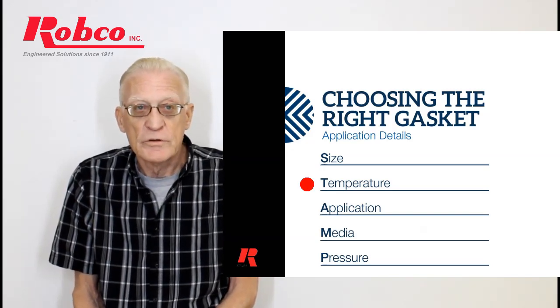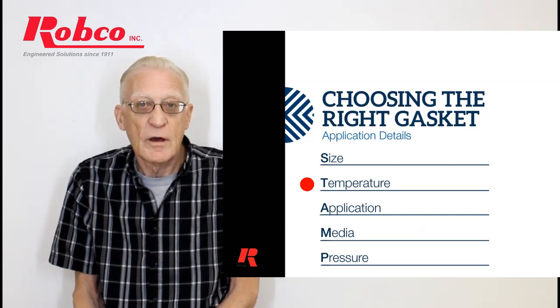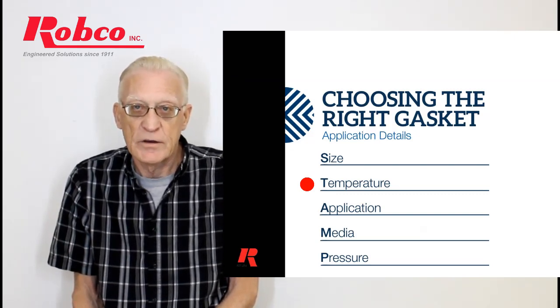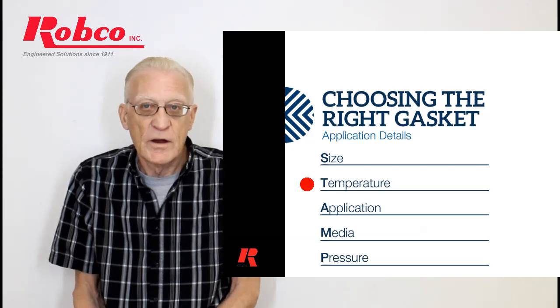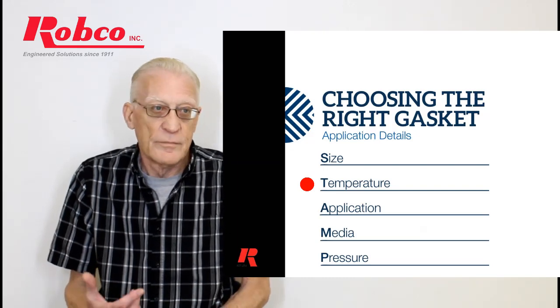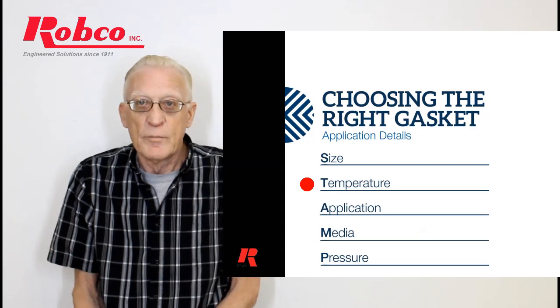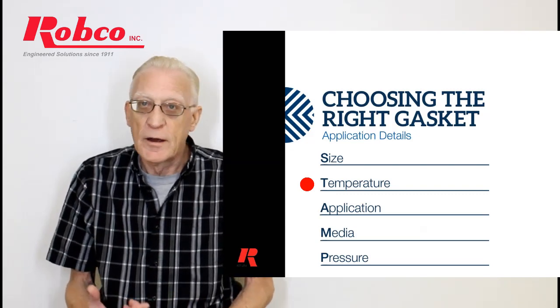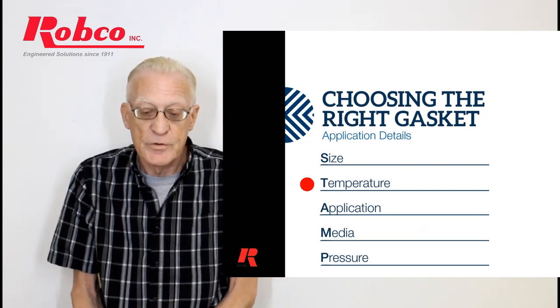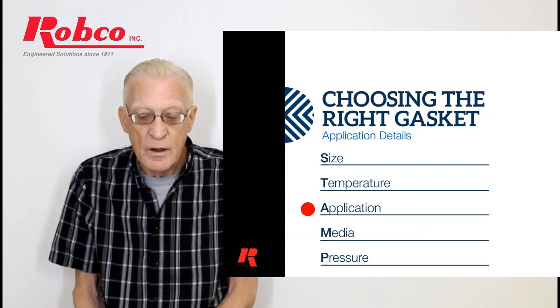Temperature, extremely important. Temperature, of course, they all have limits. I believe in safety factors. If it's 500 degrees, and the gasket's good for 500 degrees, well, don't use it. You're going to get variations in a line, you're going to get equipment holding up and pressure building up. As pressure builds up, temperature goes up and so on. Always build in safety factors on temperature.